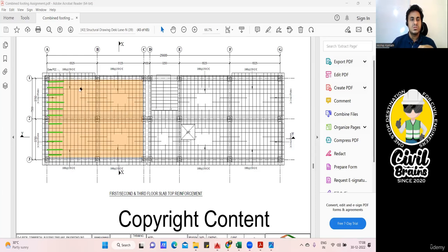Okay, fine. So this side I did. Similarly, do we agree that we have to do this on this side also? Again, on this side it will come like this. The bar will be placed from beam inner to beam inner, from this point to this point. It won't come on the beam. So this cutting length we want to find, and also we'll find the number of bars.